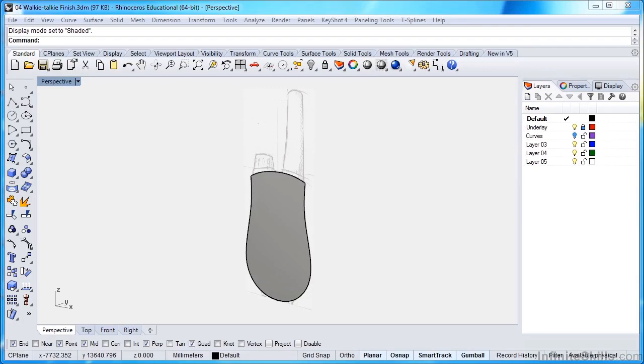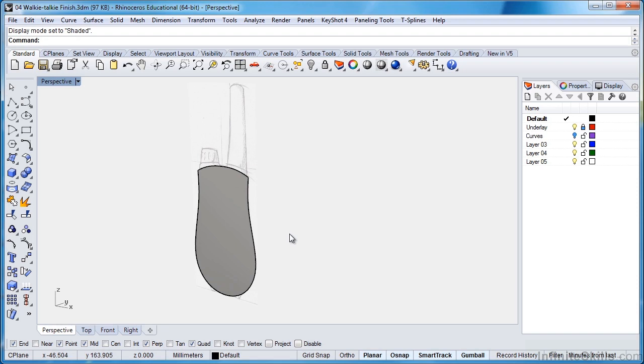In this lesson, we'll continue building our main body. So we have our front face already built, and we're going to use that same face for the back surface. But we want to make sure that we get the correct offset to use. So what I'm going to do is take the surface we've already created, and I'll use a command called extract isocurve, which is this icon right here.